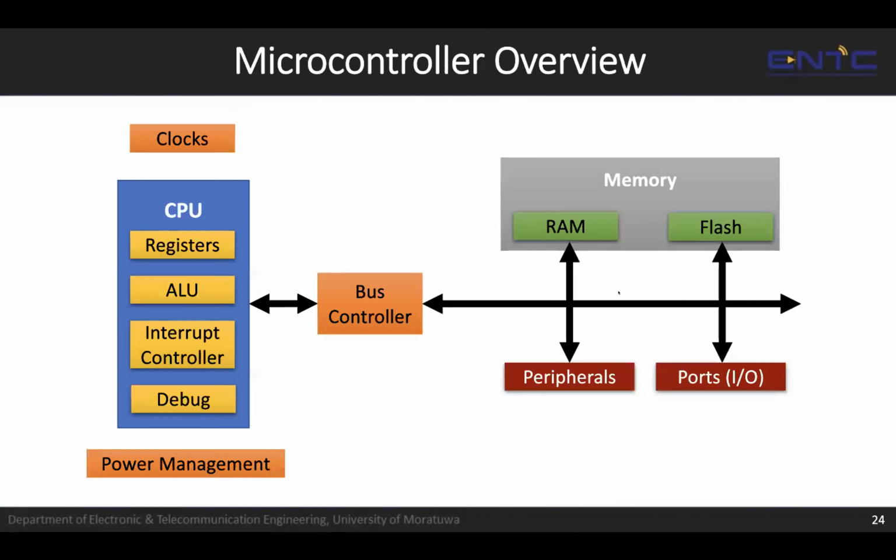So when talking about this processor, one instance or one solution for this processing core is a microcontroller, right? And another solution is a microprocessor. So we explained to you the difference between a microcontroller and a microprocessor. Here you can see it has registers. These are memory locations where you store the instructions and the data to be executed. There is a clock subsystem that synchronizes everything. There's power management. There is a bus controller for communication. There is memory and external input-output as well. So this is what a typical microcontroller looks like.